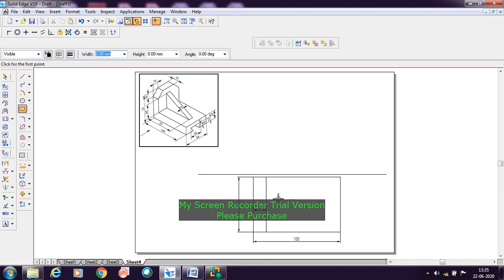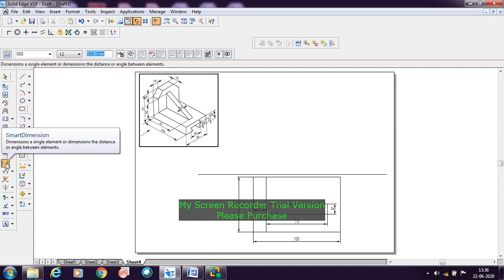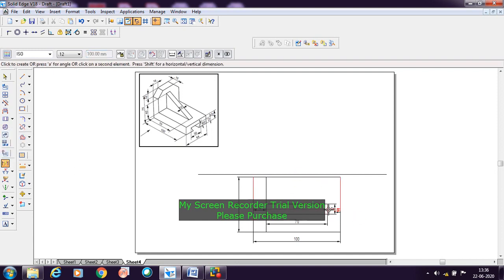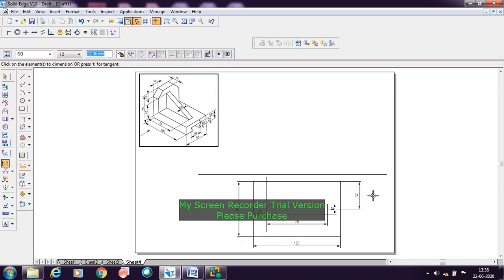Now in this case I'll be drawing the rectangle here. The length from here to here it is 70 mm here. So I'll take 70 here. I've taken the length equal to 70, and then the thickness it is 12 mm here. So take the thickness 12 mm here, and here it is centrally placed in between this width 64. So for that I'll be fixing the dimension here. From this edge to the midpoint of this, I'll be taking this as 32 mm here.